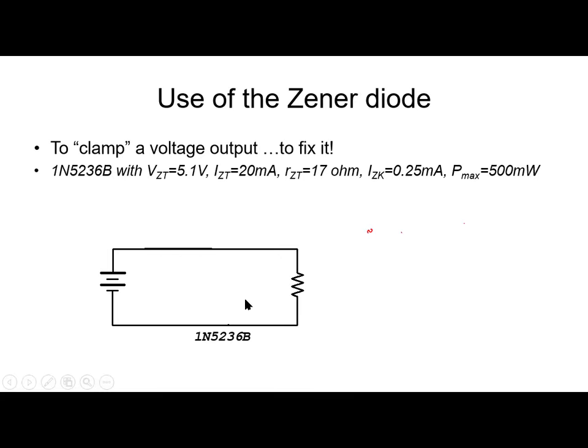There is the original circuit. We have a battery there with a voltage that oscillates. Sometimes it's 12, sometimes it's 14, depending on external factors. And we have a load that varies its value between 330 and 1000 ohms. Between them, I will include a Zener diode like so. Observe the polarity, and to limit the current in the Zener, we have a limiting resistor of 100 ohms.